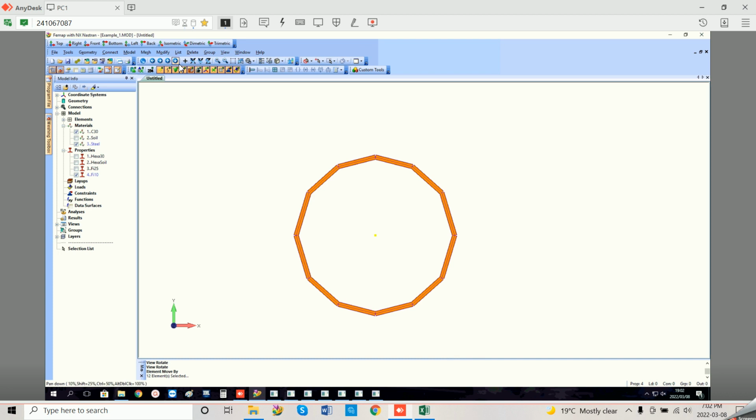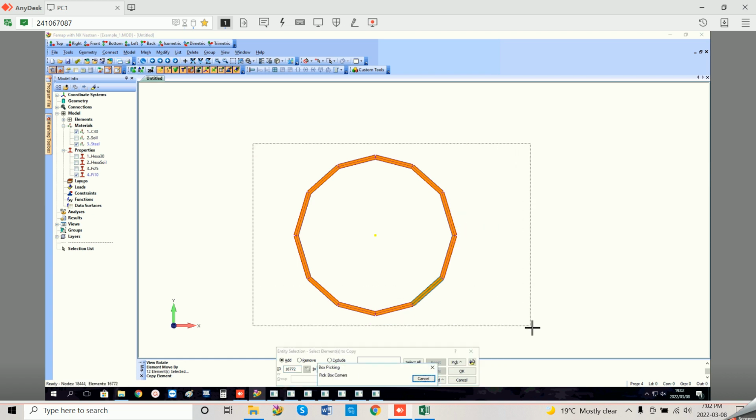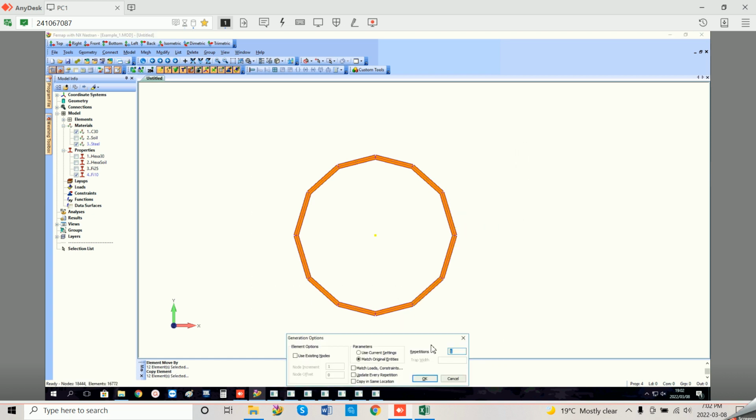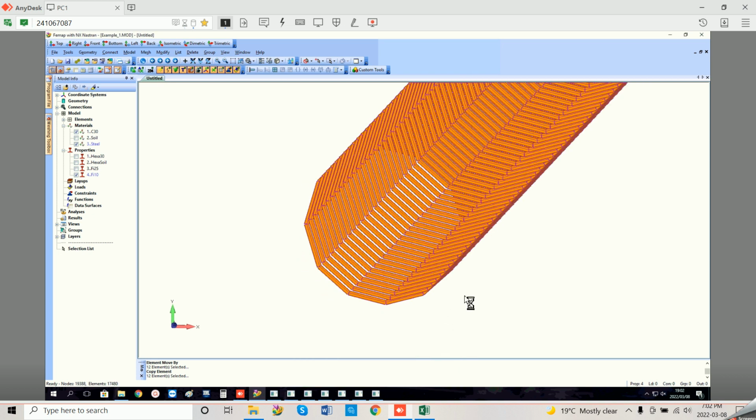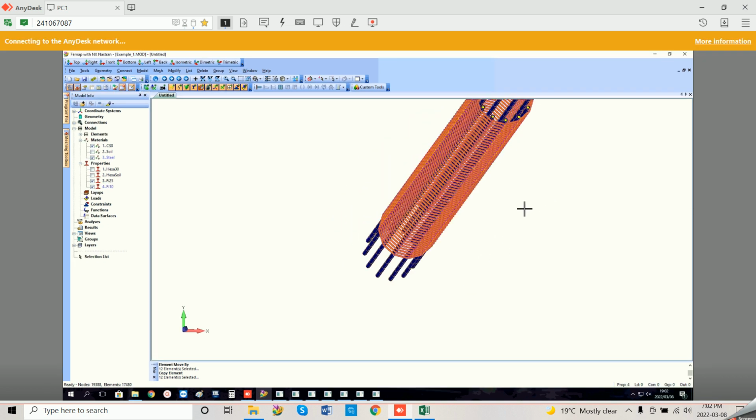And now since there are 60 elements, therefore, remember we said we're going to put it at 100 mil spacing, so that means we're going to have to copy this 59 times. So copy, repeat 59, negative Z, and the spacing will be 0.1. So there we go, it is copied all that. I can put on the bars. Oops.